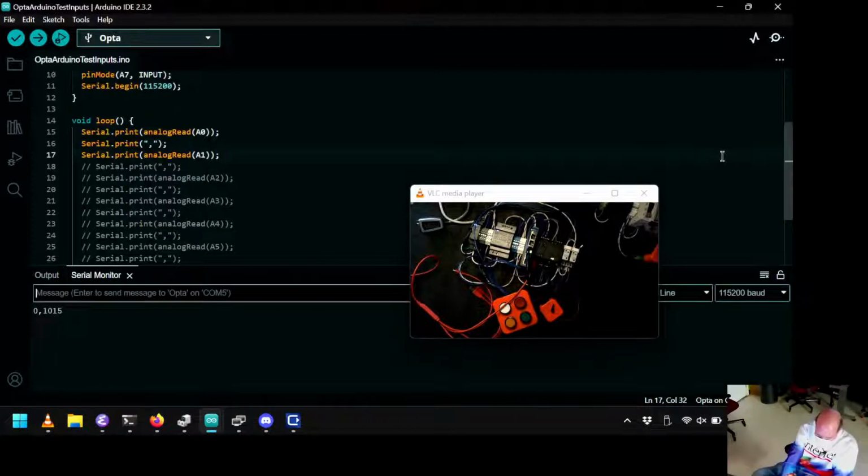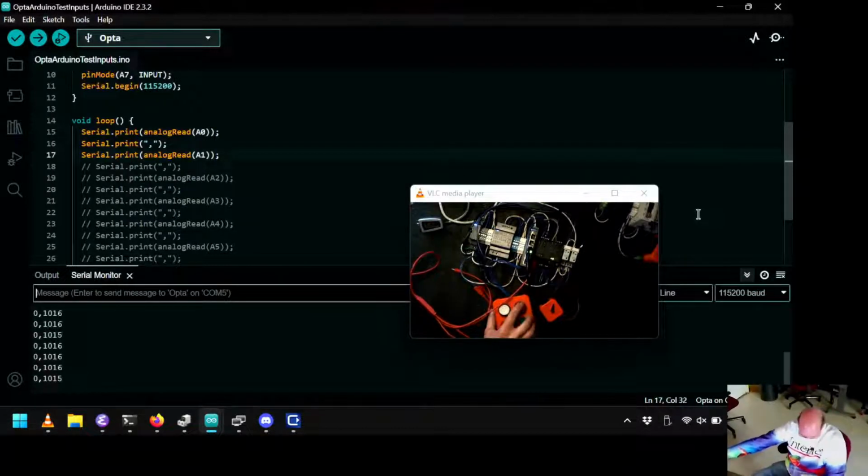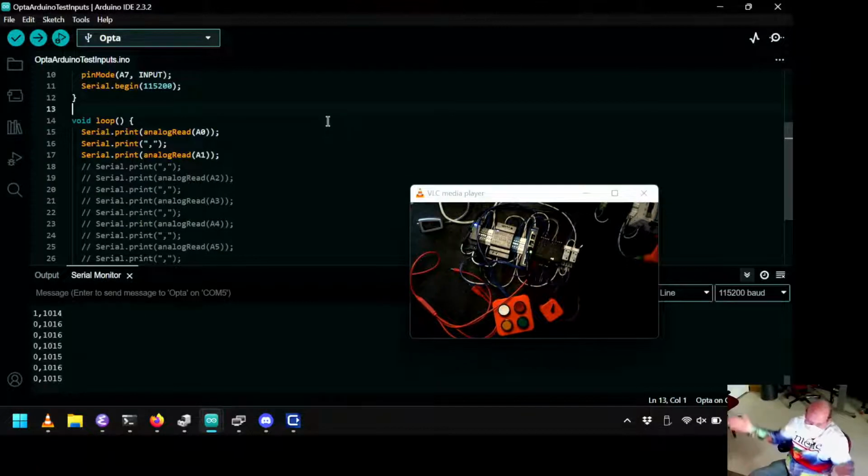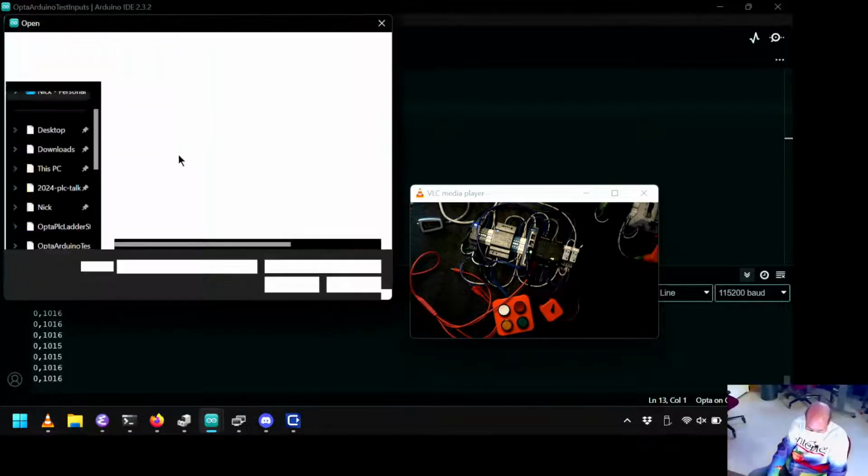I'm going to bring up the serial monitor, and one of the inputs, the red button one, is high and goes low when I press the button, and the other one is low, goes high. So it's an Arduino, but it's in a funny shape, and it doesn't have shield headers, and I can't plug quick stuff into it. Why? Because of the relays.